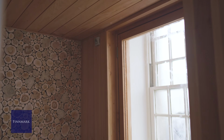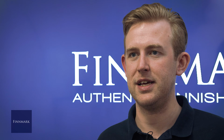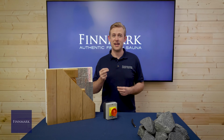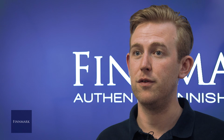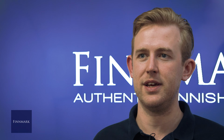Windows are a game changer in terms of sauna aesthetic, but often little consideration is given to the impact that these have on the computational volume of a sauna, and in turn, the power of the sauna heater required. For example, for every square metre of single glazed glass in a sauna build, you should add 1.5 cubic metres to the volume or capacity of the sauna.